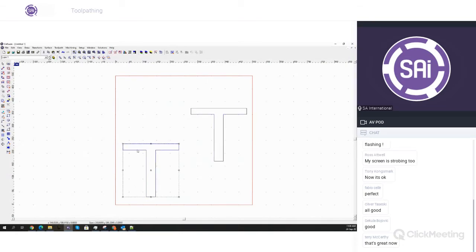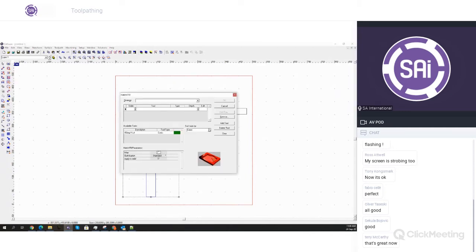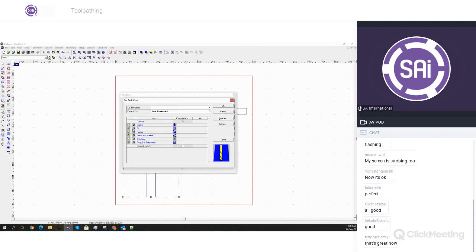So let's say we want to mill out a pocket here. For this one, we would probably take a hatch fill or an island fill. We'll take an end mill. Let's do the 4 mil down shear. Let's go to a pocket depth of 8. Let's do 4. Our fill, since it's an end mill, depending on the material, you can lower this by a lot. In this case, I'll just put it 20% overlap. These ones we'll cover in a bit.